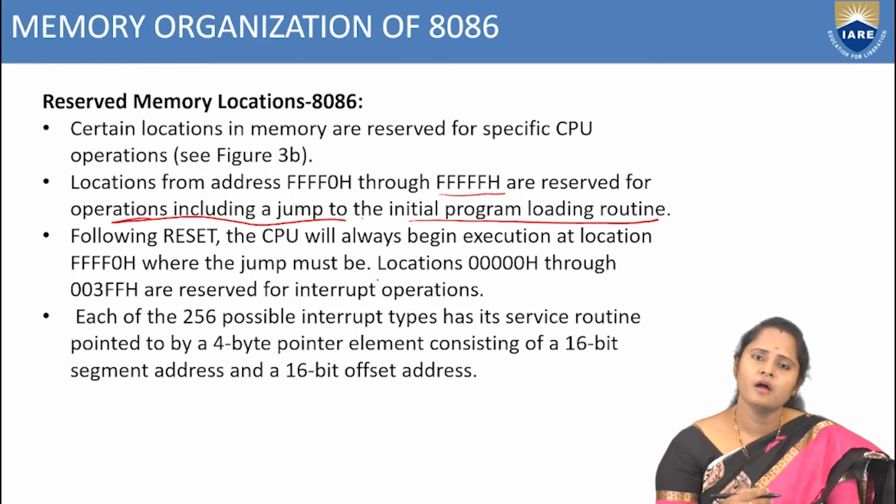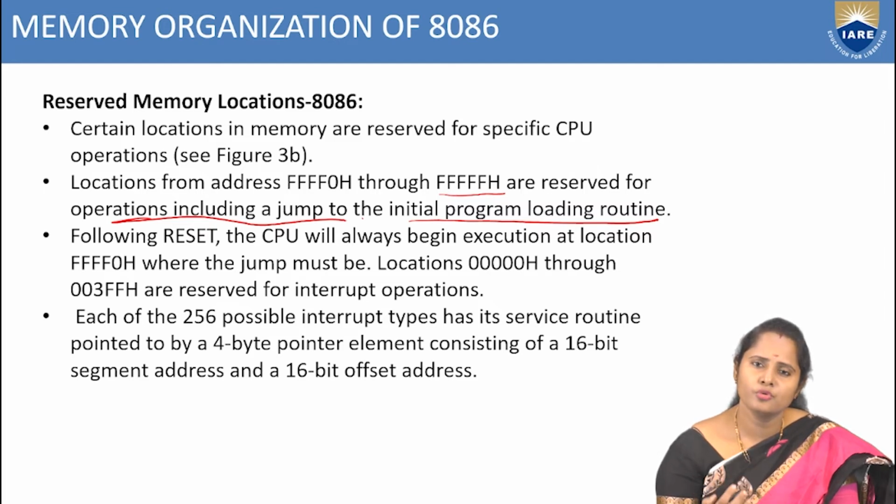Suppose I need to use this reserved memory location. Whenever my CPU goes to reset mode, my address location will begin from FFFF0.